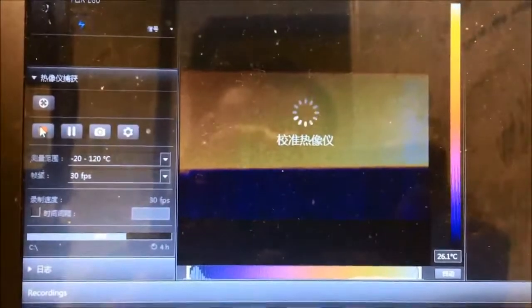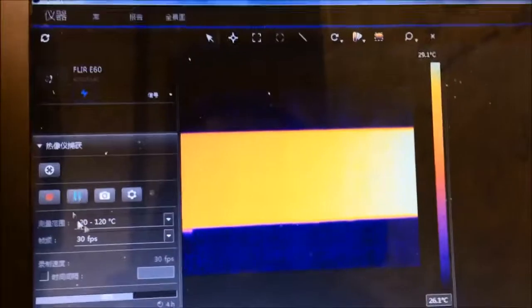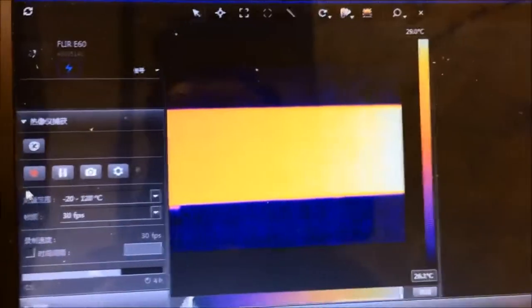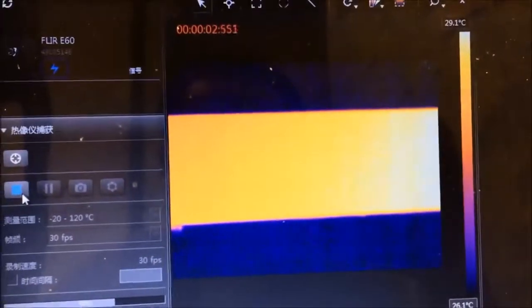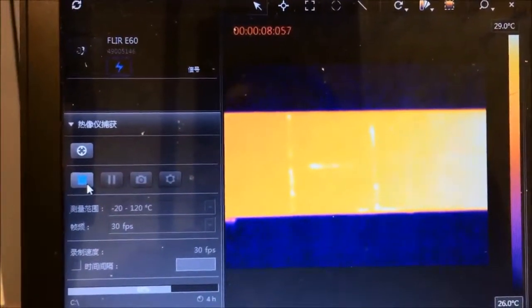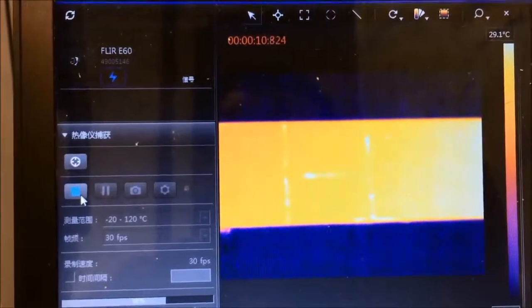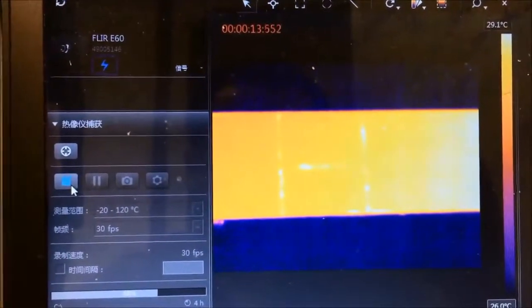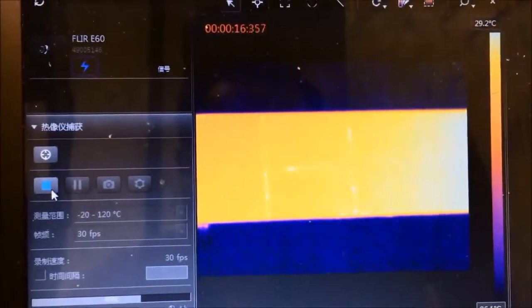The following is an experiment using vibrothermography for crack detection. The total time of the experiment is 20 seconds. We will start the ultrasonic excitations at the 5th second and stop them at the 15th. Let's begin the experiment. No excitation will occur in the first 5 seconds. The excitation starts, and you can see the cracks beginning to form in the video. The excitation will stop, and the cracks will no longer be detected.